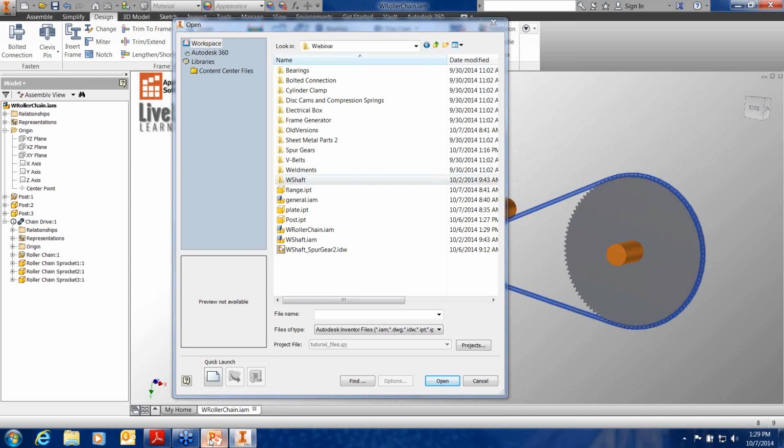Okay, one thing on the naming there, you do have that option. I was just letting Inventor name it, but you do have the options to change those names. There is a setting that you can hit that will prompt you for the names. I don't know if you've ever used, for instance, the frame generator. You can set it up that as you create the parts, it will just automatically name them, or you can have it set for you to name them yourself.